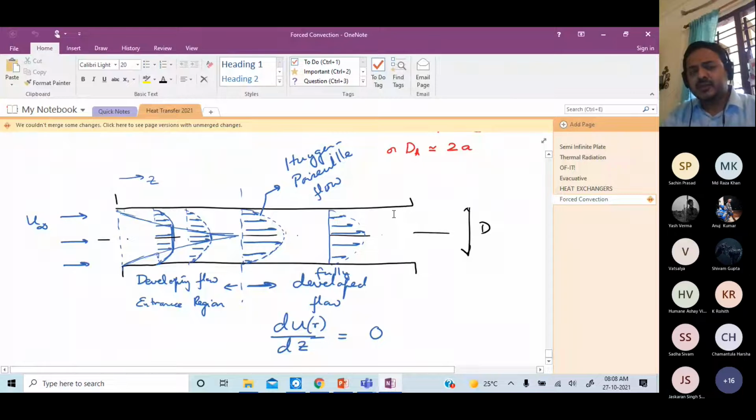That is because of what we were discussing in the last class. In a flow over a flat plate, the momentum boundary layer keeps growing and increasing. Whereas for flow inside a pipe, these boundary layers start developing on all surfaces. And at some point of time, the effect of the viscous forces at the walls penetrates right into the center line. As a result, the boundary layers start interfering, and thereafter it cannot grow any further.